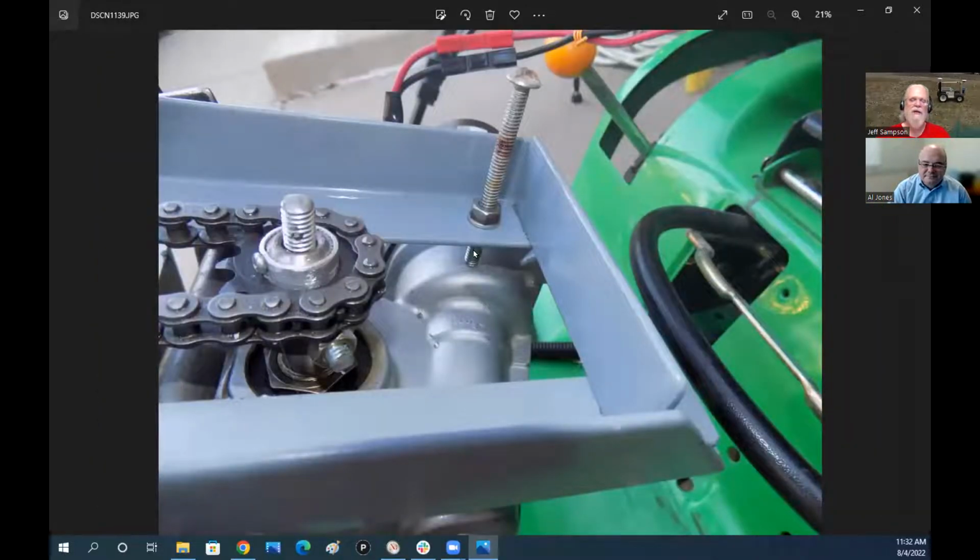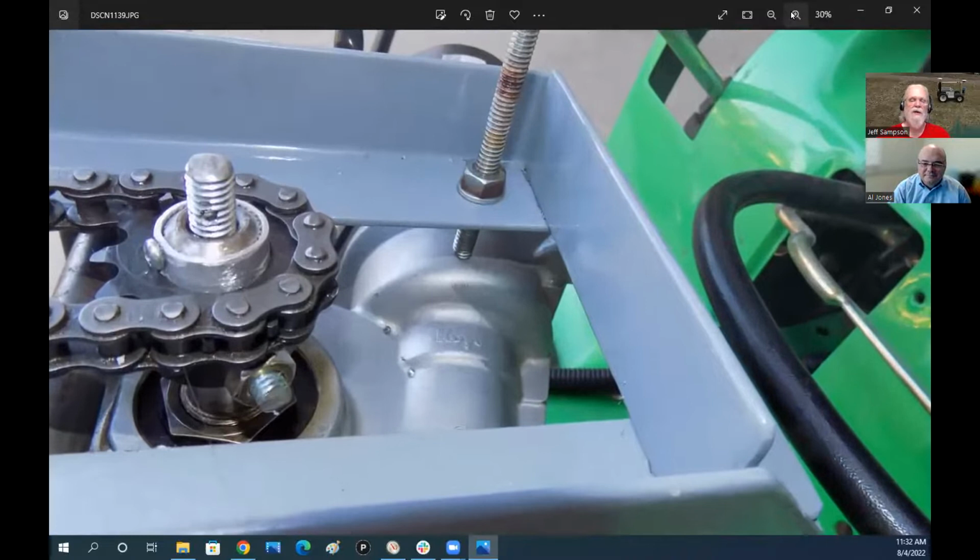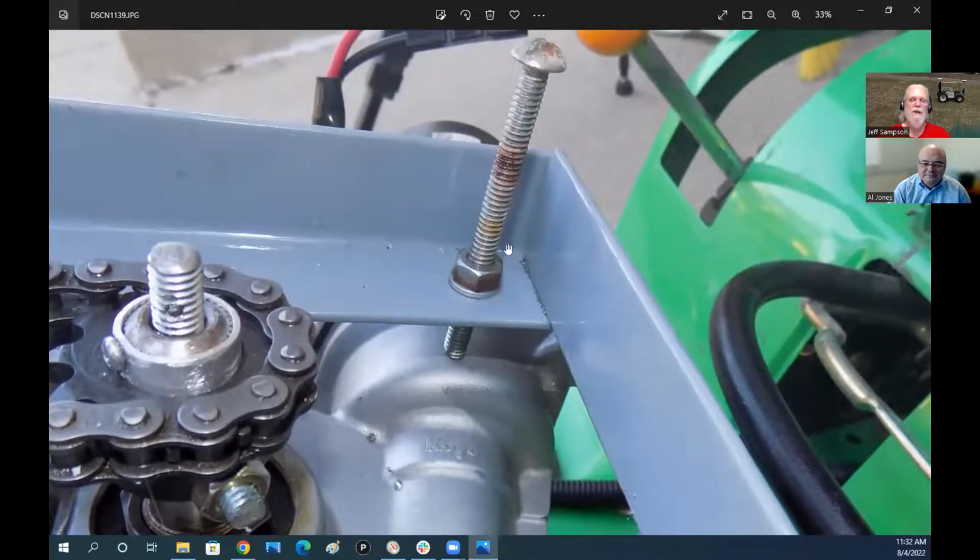And there's the picture of the, here, can I zoom at this point? Yeah, there I can. So essentially I just looked at it and said, okay, here's about the center of the motor housing, and I tried to keep away from the edges so I can get a wrench on it, and I just drilled a hole through there and tapped it, and then put the bolt in.